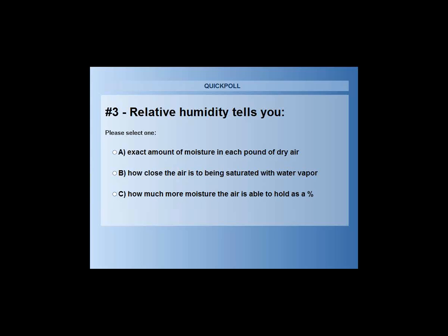In an existing system, it may not be possible to slow it down that much if you can't get air to the furthest duct run, right? So if the system was designed for 400 CFM per ton and you drop it to 300, you might be great and it might do a great job. However, you might have situations where you can't get air to the furthest zone. In a residence, that's going to be the bedroom at the end of the long ranch house or the bedroom above the bonus room garage type thing. So you've got to make sure you can still get the required airflow out to those places. But if you can, start dropping that CFM down.